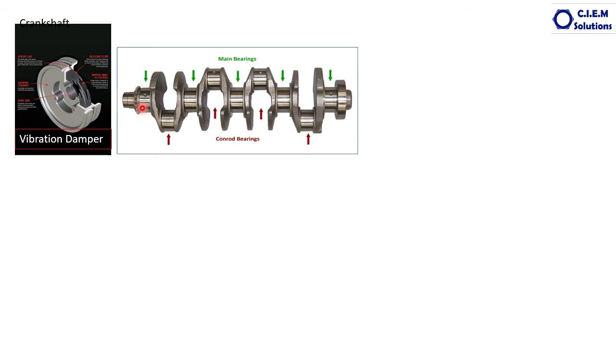When the engine is running, as I told you, because of the continuous heating on the piston crown, a lot of vibrations are transmitted to the crankshaft. Okay. And when it is rotating, a lot of torsional vibrations take place. Torsional forces take place. To protect the crankshaft from breakage or crack, there should be some element to absorb the torsional vibrations. That particular item is the vibration damper.